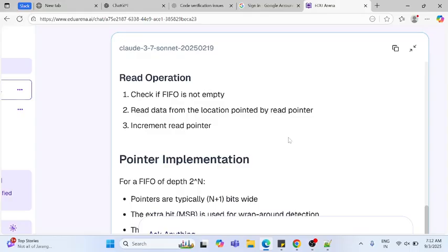Now it is our turn to read the data. Once you are reading the data in locations 1, 2, 3, 4, 5, 6, 7, 8, remember that random reading and writing is not possible with the basic FIFO structures. There may be a possibility to add something, but that is not widely used. We don't have an address. In fact, the purpose is different: writing sequentially to a particular depth of the data and then reading it. That is what happens with respect to a FIFO.